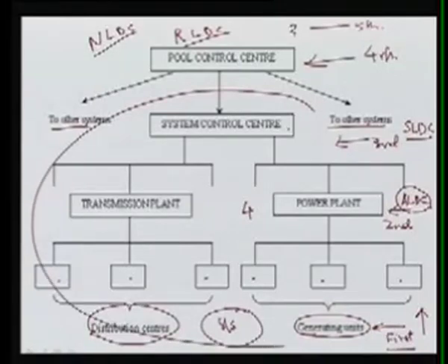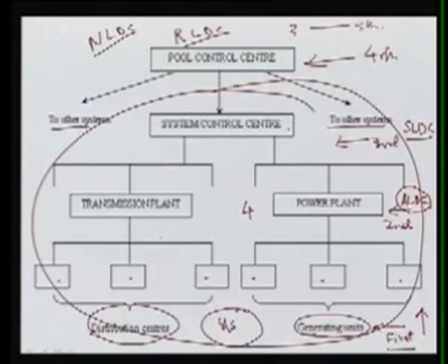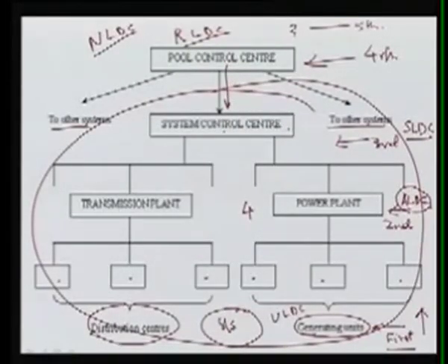Here, this state is one state, and they are going to monitor. Normally the RLDC never interferes in the individual operation of these load dispatch centers. Here you have the first level, basically called your unit load dispatch centers of individual substations. Then it comes to the state level, and then they provide the information to the various units. So this is your control hierarchy of your power system.